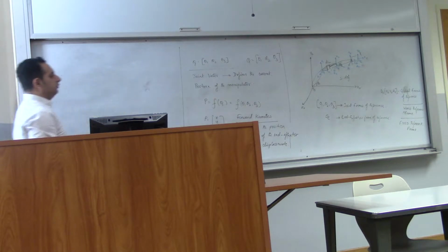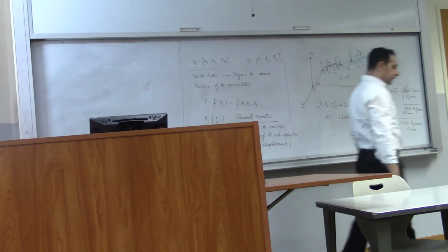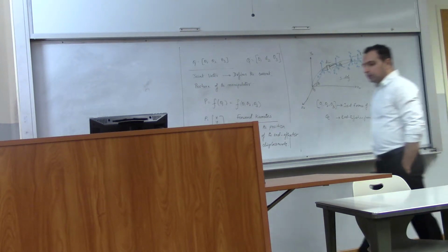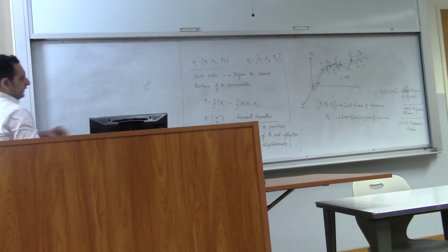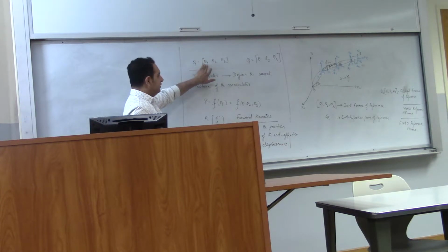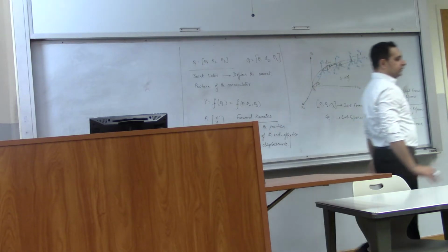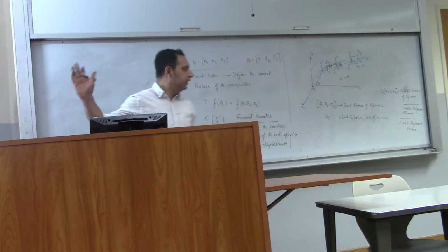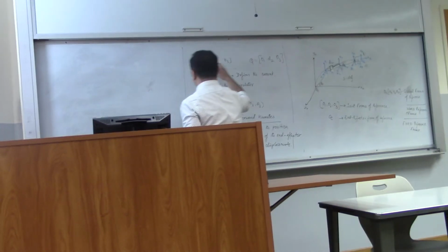Okay. If one of the joints, instead of revolute, becomes a prismatic joint, then you'll change theta to D. D reflects your linear motion, theta reflects your angular motion. So when I say a joint displacement, it is understood that if it's a revolute joint, it's an angular displacement. If it's a prismatic joint, it's a linear displacement. So we're not going to argue about why I am writing theta or D. It is assumed that if this joint is D, then this will become D2 and so on.